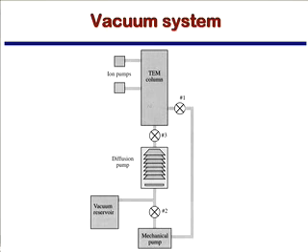The first thing that you will do is turn on this mechanical pump, the roughing pump, the scroll pump, whichever you have, and this thing will pump along the line on the right, and at some point you will open up valve number 1 here, which will allow you to evacuate the TEM column through the rough pump. And you will go from air pressure, 760 torr, down to the 10 to the minus 3 regime.